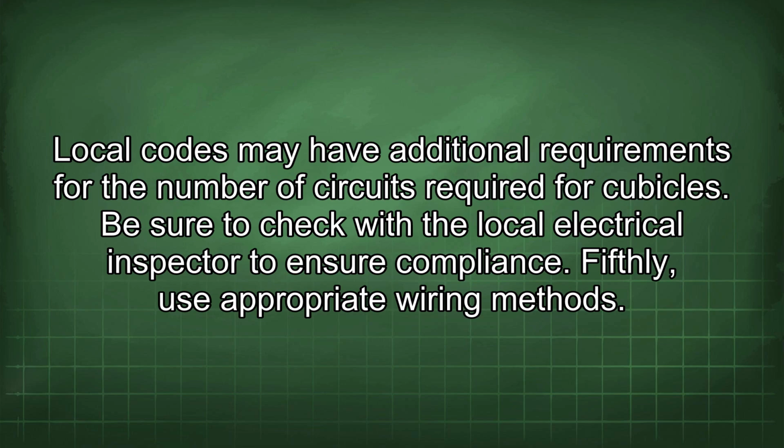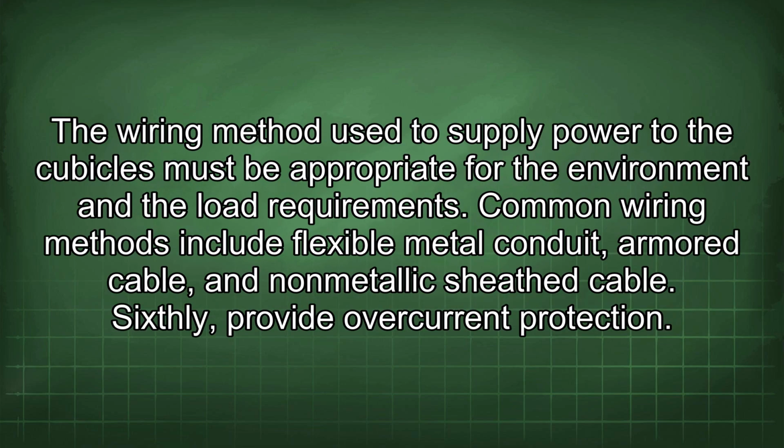Fifthly, use appropriate wiring methods. The wiring method used to supply power to the cubicles must be appropriate for the environment and the load requirements. Common wiring methods include flexible metal conduit, armored cable, and non-metallic sheath cable.